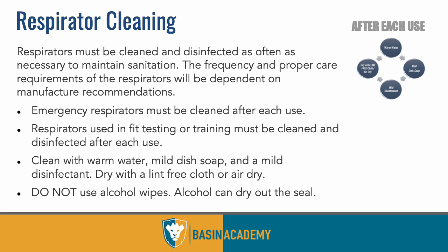That's pretty good on a day in, day out basis, but at least once a week, if you're using this thing a lot, you want to wash it more thoroughly. Bacteria can get in there, start growing, you get a colony, you put on the mask, you breathe it in, you get sick from your respirator. That's not a good situation.